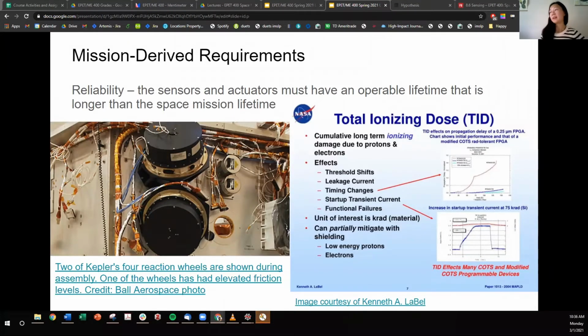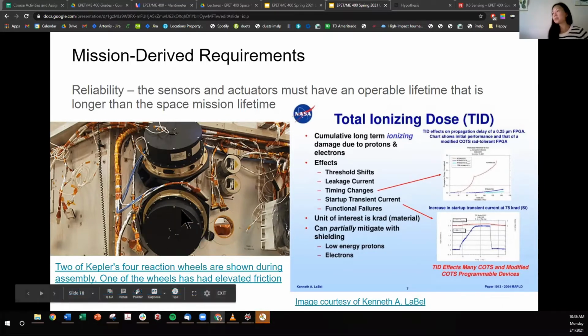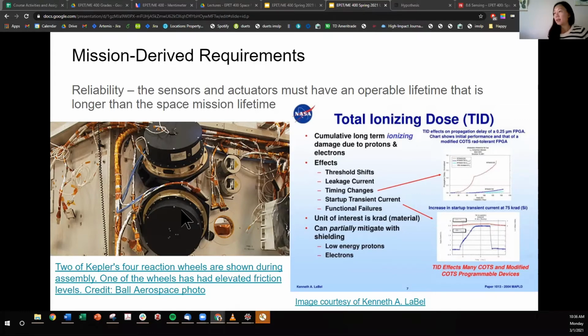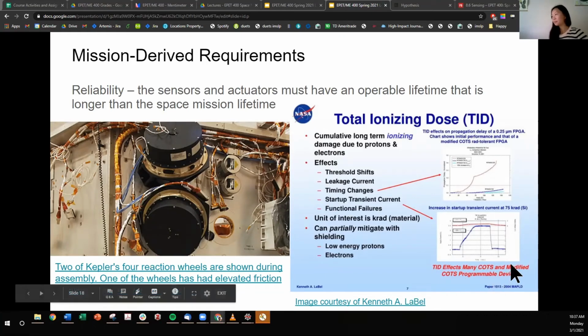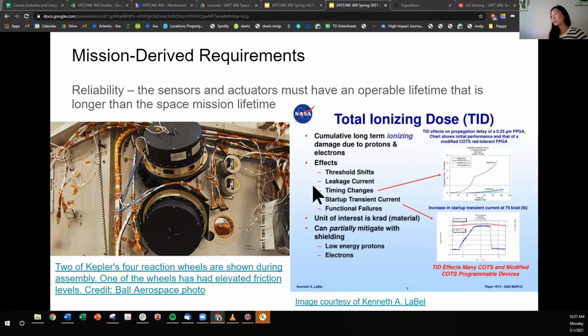Okay, sorry. So yeah, regardless, reaction wheels can fail over time. There's a lot of mechanical motion that's inside, there's a lot of friction, and so the lubricants can disappear or the structure itself can wear down, causing abnormalities within and then causing it to fail. It could also be that radiation causes sensors or anomalies within materials to fail.